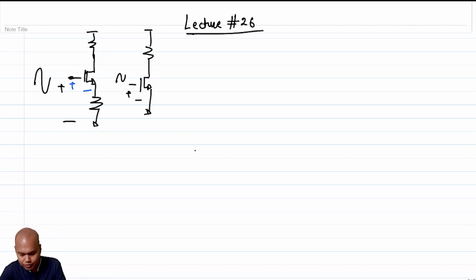So given what we know about the distortion producing mechanisms in our circuits, we understand that one of the primary reasons for distortion is the modulation of the VGS, which while giving rise to gain also introduces distortion. So we'd like to keep that modulation as low as possible. So clearly the circuit on the left gives you an intuition that it will probably have better distortion characteristics, right? But however, there is a catch.